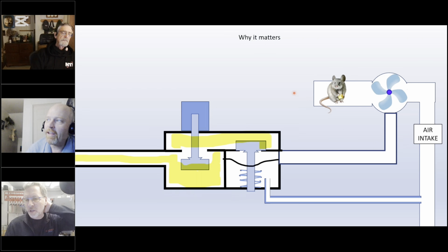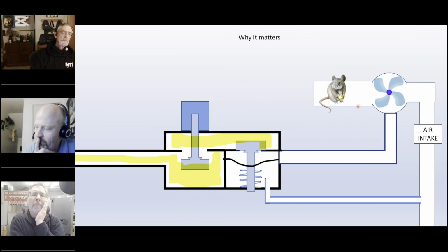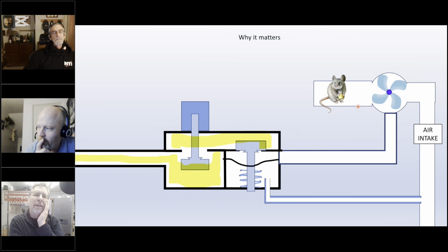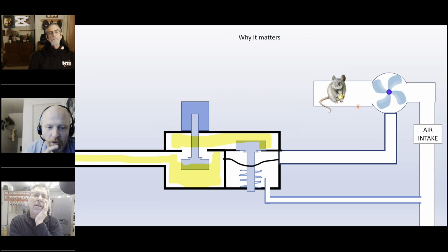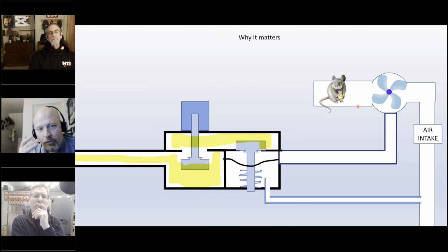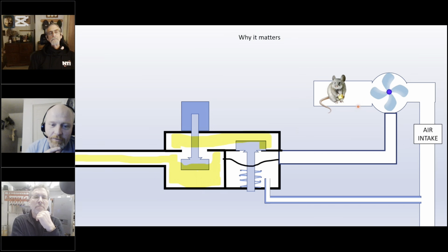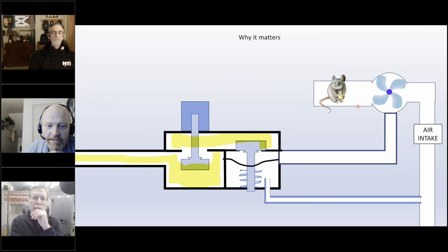It's very low. Could you do that by just disconnecting the low voltage wiring going to the blower so it runs at full speed? You can, but the pressure readings are going to be higher than what I indicated, because at that point you're actually over revving the fan. You're running it at maybe 125% of its capacity. So because you're trying to move more air, you're going to create a bigger pressure difference. But certainly you could.